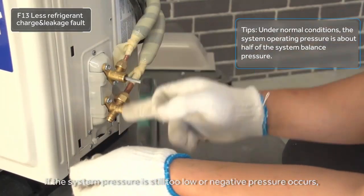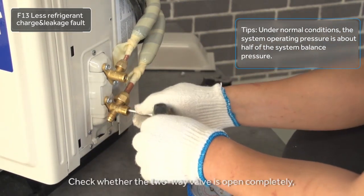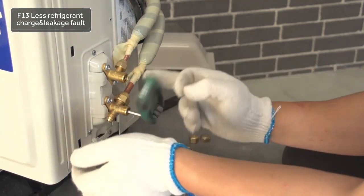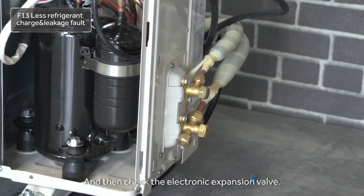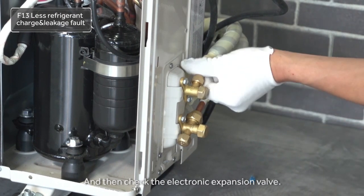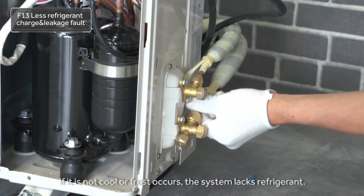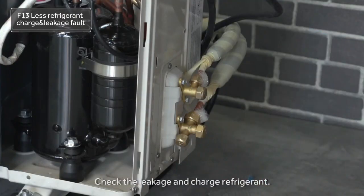If the system pressure is still too low or negative pressure occurs, check whether the two-way valve is open completely, and then check the electronic expansion valve. Check the two-way valve. If it is not cool or frost occurs, the system lacks refrigerant. Check the leakage and charge refrigerant.